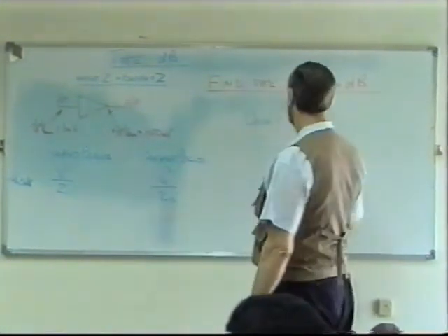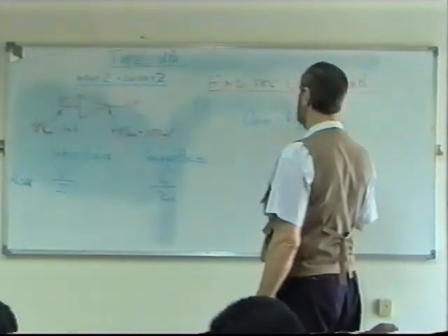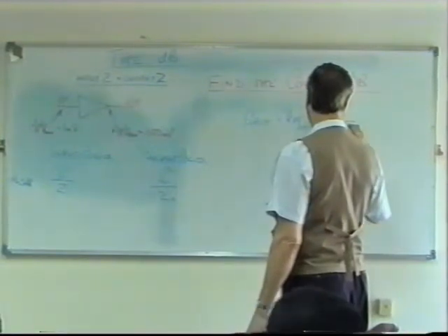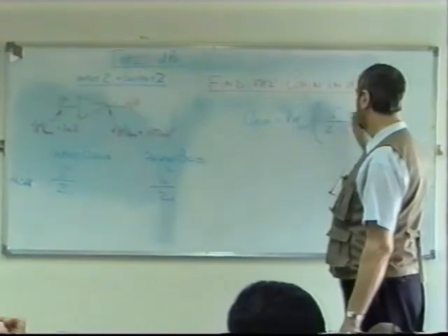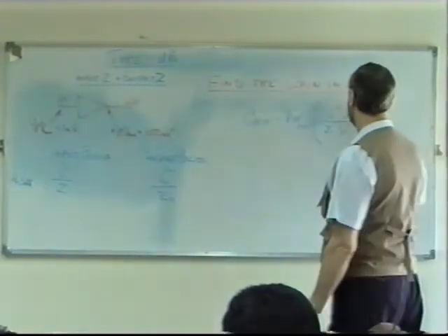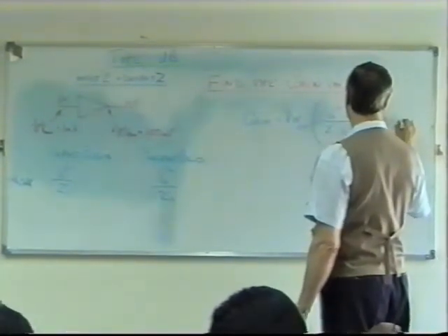So it's V output squared over Z divided by V input squared over Z. Well, the Z's cancel, don't they? We can ignore now the actual value of impedance. And then, of course, we multiply that by 10, and that gives me the answer in dBs.